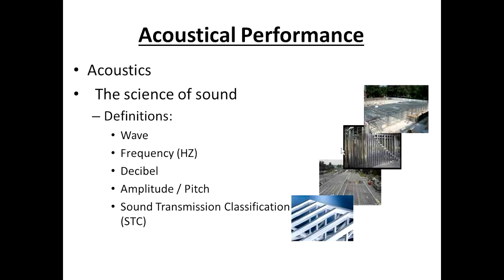And you're probably wondering why I've got pictures of steel framing alongside this basics of sound, because the last bullet we're going to talk about is sound transmission classification, and that is a single number rating system that gives us a comparative way of evaluating different assemblies for impeding the flow of sound through them.